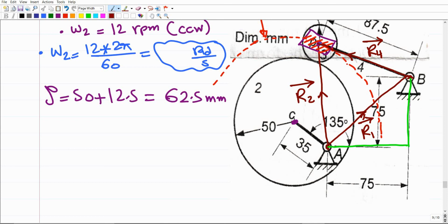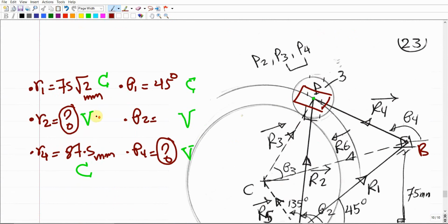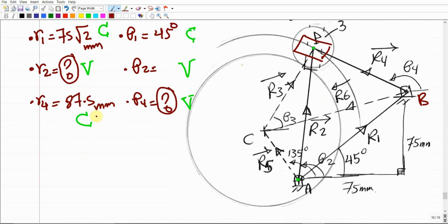Make sense? So we can do some trigonometric calculations to find theta 2. The thing that you should understand is that theta 2 is indirectly given. It is acceptable to do this trigonometric calculation to come up with the value for theta 2, or simply you can deal with theta 2 like a third unknown. So we do have 3 unknowns here, so we weren't going to be able to proceed. So we need more loops. We need another loop, one more loop.